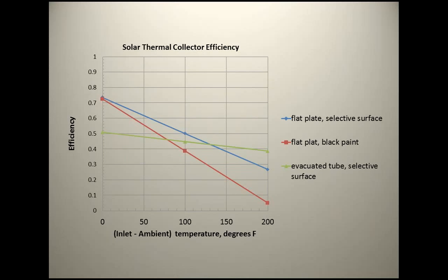If you remember, on the tube collectors, there's all kinds of spaces between the tubes. So this is energy per unit of surface area. And the tube guys probably complain about this all the time, because they say, well, if you just use the surface area of the tube itself, your efficiency would be much higher. But because the calculation is done per surface area, a lot of those tube collectors have slots between the tubes, and so there's no ability to collect between the slots. And so their efficiency numbers are low for that reason. So you can change this up and down depending upon how you account for the slots between the tubes.